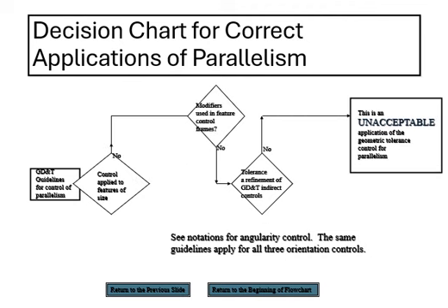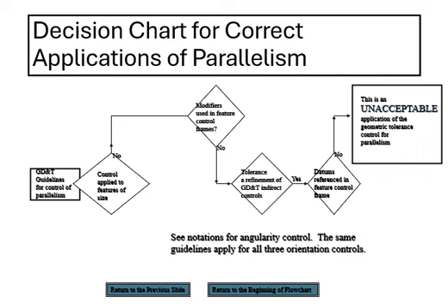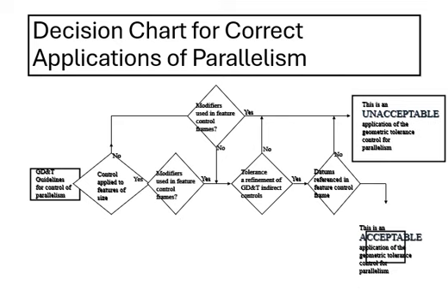You look at feature or feature size, it is feature this time. Look at the modifier, you don't have the modifier, so that's okay. Catch that. And you look at the tolerance, and you don't have the tolerance, so therefore it's not acceptable to control parallelism, yeah? And if you do have the tolerance and you look at the datum reference, if you don't have the datum reference, it's not acceptable. Now we look at feature size or feature. It is a feature, okay? If that's feature size, go this way. If that's a feature, go this way.